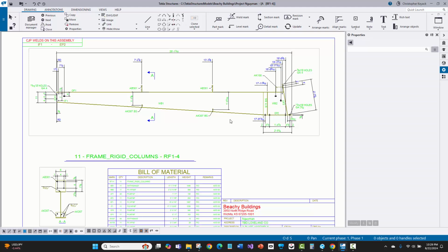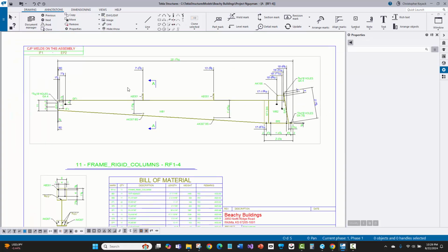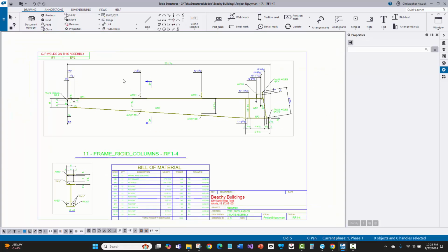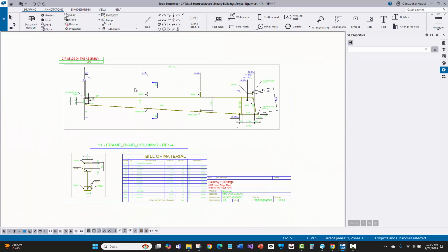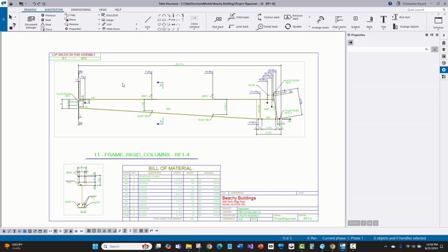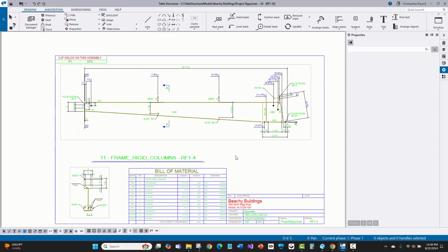Here I could save up to 10 minutes just smart creating and only moving one dimension and then moving on, rather than cleaning up the same drawing just because of one moved clip. Now, the cloning or the smart create doesn't always work. Sometimes this flips itself on its head and you actually burn more time dealing with the clone drawing, trying to find all the little things that might be wrong with it and fixing it, versus just going back to the automated dimensioning settings and cleaning up the few things that you know you need to do.